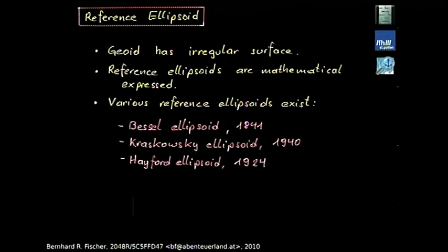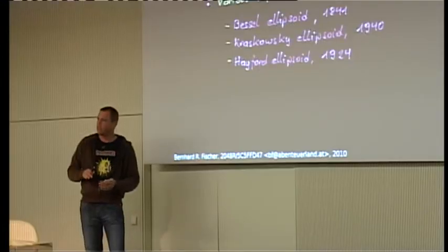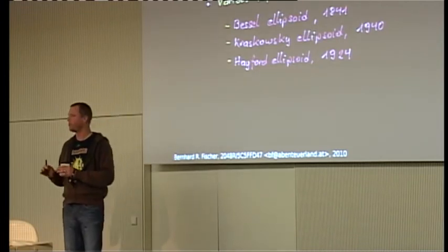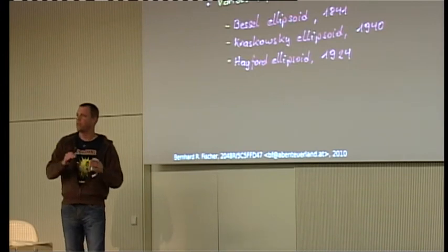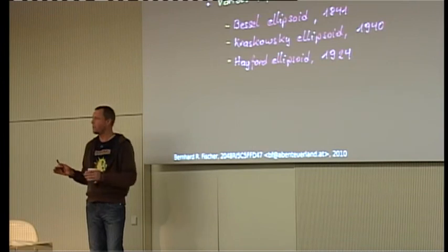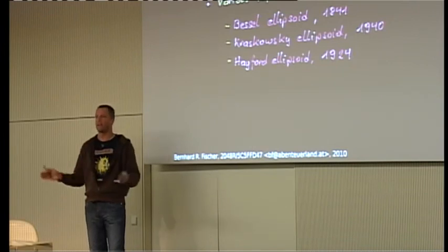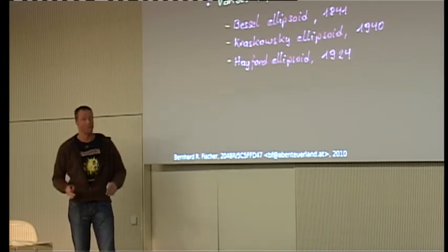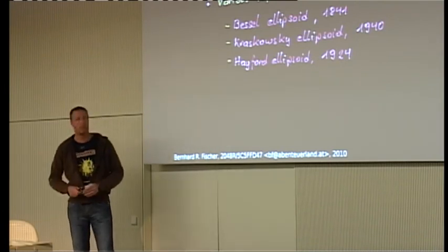What they continued in history is that this ellipsoid of revolution is a generic model, but they found out that we can calculate different ellipsoid models that fit on different places on this world better or worse. So what happened is that we have different ellipsoids, and those are called the reference ellipsoids. There are several of them. I just picked out a few of them.